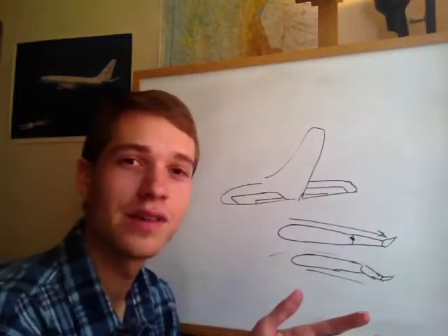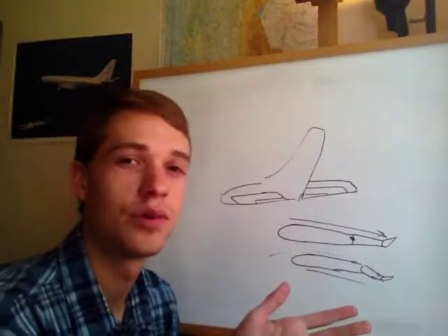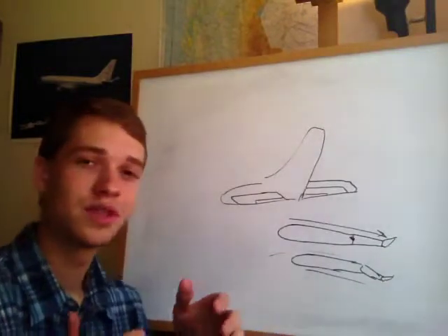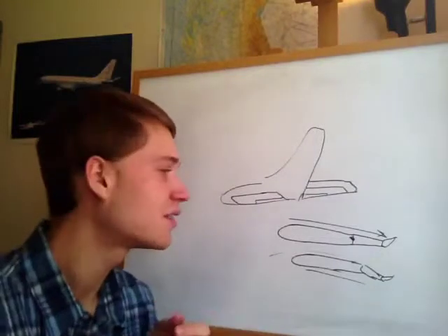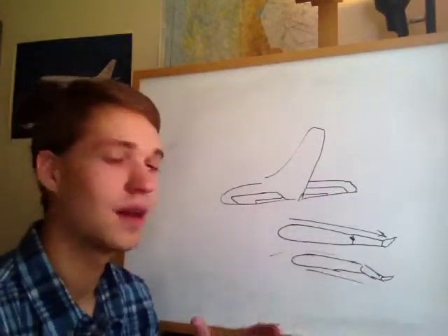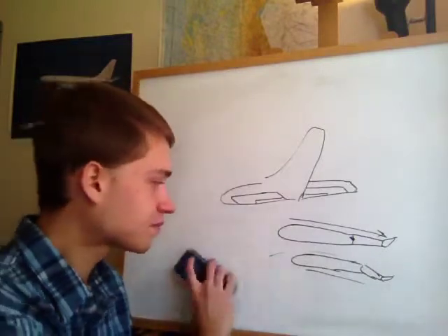Of course, the airplane is always going to need retrimming because some little thing will change. You'll burn off more fuel. Somebody will shift around in their seat, maybe move their seat back, and so the airplane will be a little bit out of balance again. But this is how we can make flying a lot easier by changing the trim tabs.